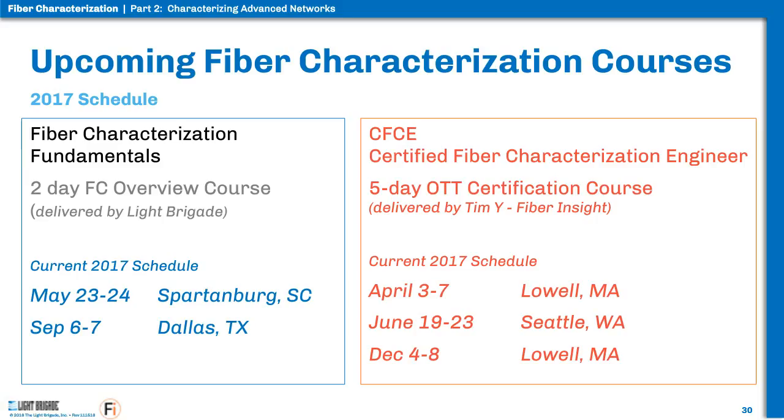So in one direction you'll have a gain. For instance, if I go from G652 fiber to G655 fiber on my link, it'll actually show an apparent gain when I shift to that. If it's a section that's spliced in that's 55, after that section is done, it'll drop back down again.